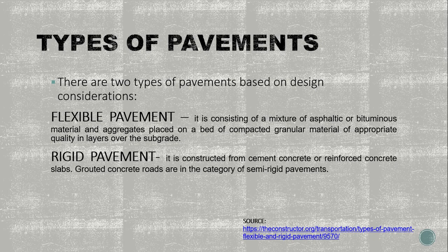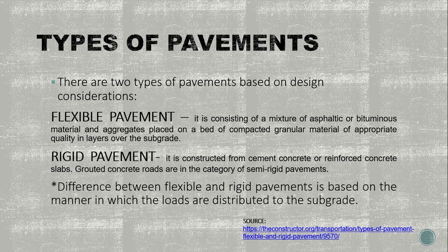Another type is the rigid pavement. It is constructed from cement concrete or reinforced concrete slabs. Grouted concrete roads are in the category of semi-rigid pavements. The main difference between flexible and rigid pavement is based on the manner in which the loads are distributed to the subgrade.